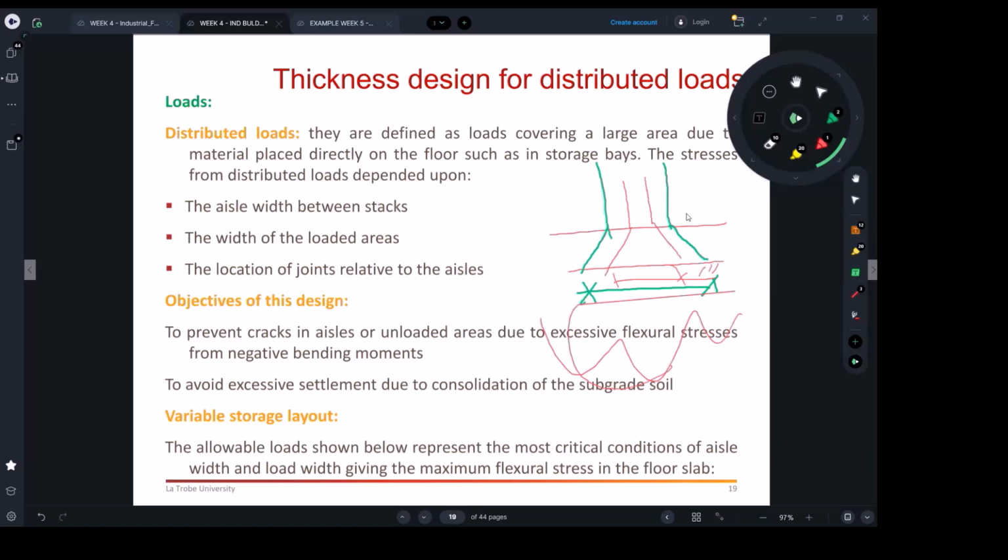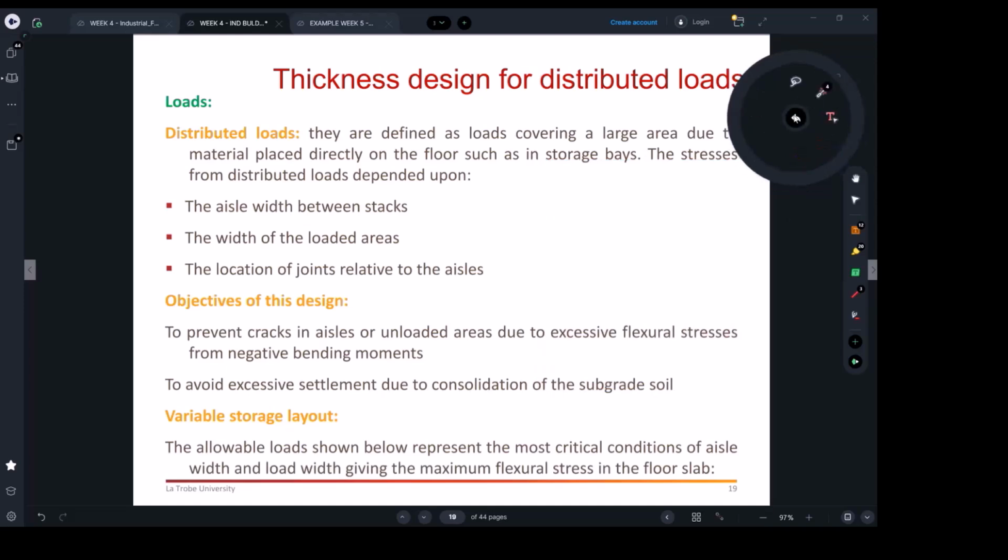That's the last point you can see here. It is to do with the control joints, the location of joints. We're talking about the control joints, as we said, at the edge of the slab or the control joints, the slab will be stressed more. To clarify this, the angle of repose I was showing you: this is the concrete slab, there's a post, right? And there's an angle of repose, which will distribute the stresses over 45 degrees.